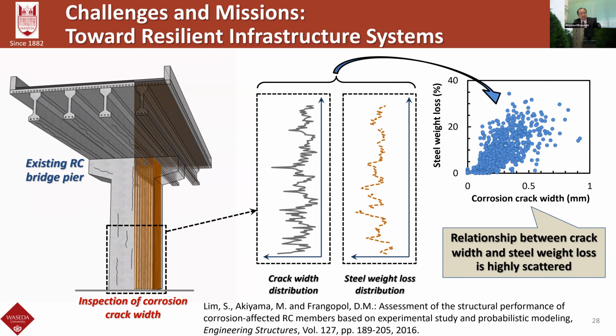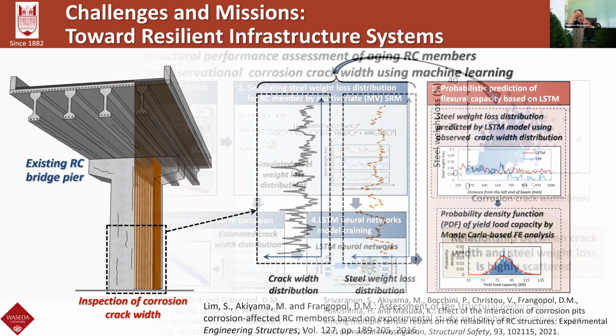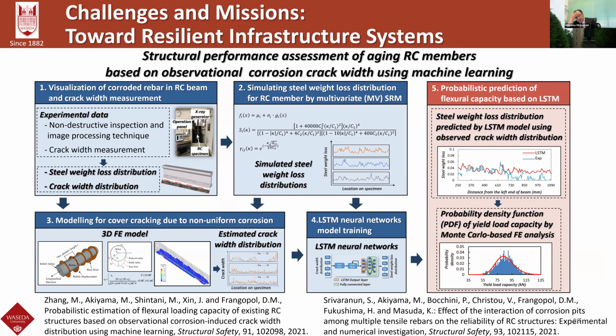So the challenge is how the visual inspection result of corrosion crack width can be used to evaluate the structural resistance. Our target is, just based on the corrosion crack width, to estimate the degree of steel corrosion, and using a numerical simulation, to evaluate the structural resistance. However, it's quite challenging because of many kinds of and large uncertainties.